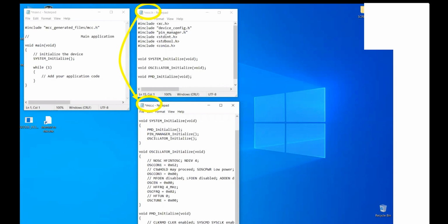And furthermore, if I then look at the includes that are included in MCC's include file, 4 of them that I've marked in red have got angle brackets round about the file name. See it, include xc.h. xc is the Microchip C compiler. That'll not bother me.